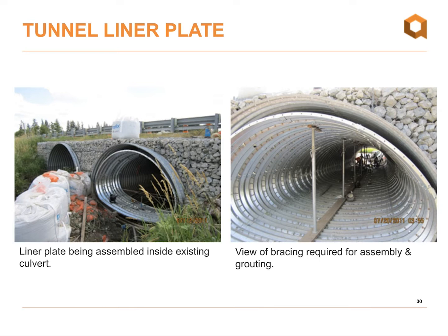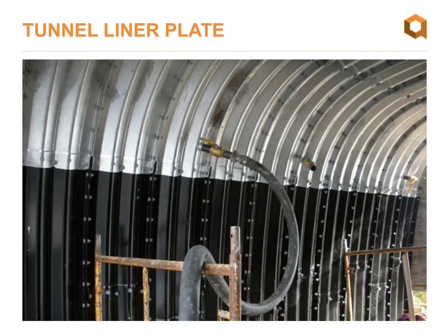So it makes it very easy when we're dealing with constrained sites if we don't have a large staging area for a slip line procedure. The photo on the right is just showing the bracing that's typically recommended during the grouting process. Again, to prevent flotation, we need some form of blocking. We also want to make sure that the plate maintains its shape as we get the grouting over the crown of the structure.